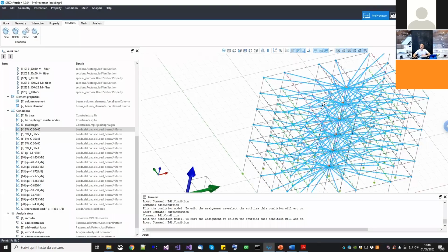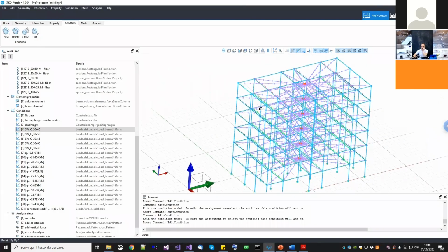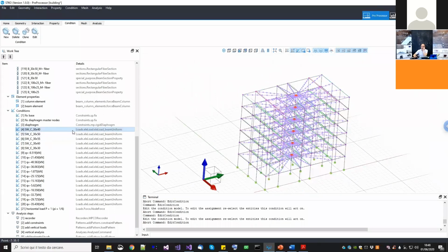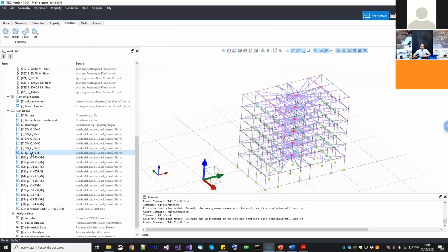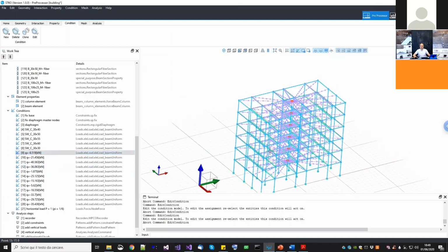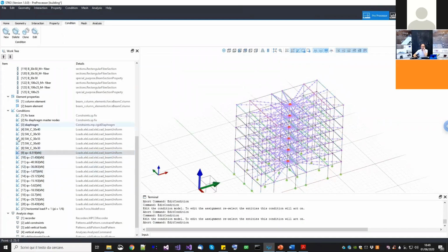And then, of course, in OpenSees, you don't have something which is called floor load. So you can create them one by one using the distributed beam load. So both for the self-weight, or also in this case, I use a naming convention. So SW means self-weight of columns. And then you do the same for the floor loads, okay? Now I want to show you just a preview, because this one has been created using distributed loads. Now here there is a mistake actually. This one is kilonewtons over meter. Okay, there was a mistake in the naming convention here.